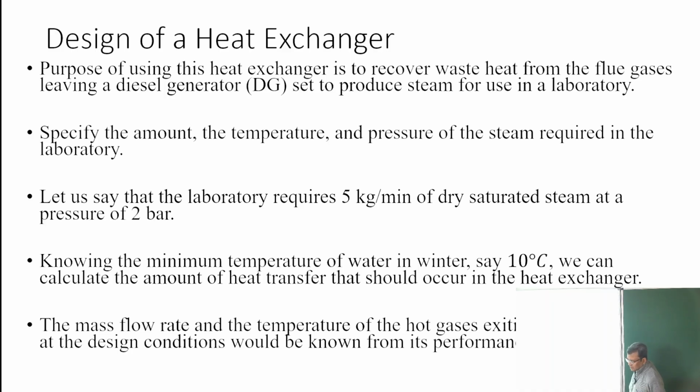So what is the requirement of the steam? That's one thing that we have to know. So if you are thinking about this picture, then you will also have to define the amount of steam that you are targeting. That okay, this much steam we need, and at this temperature and pressure of the steam and things like that. And let's say this laboratory which wants to use that steam requires steam at 5 kg per minute, and it requires dry saturated steam, okay, at a pressure of 2 bar.